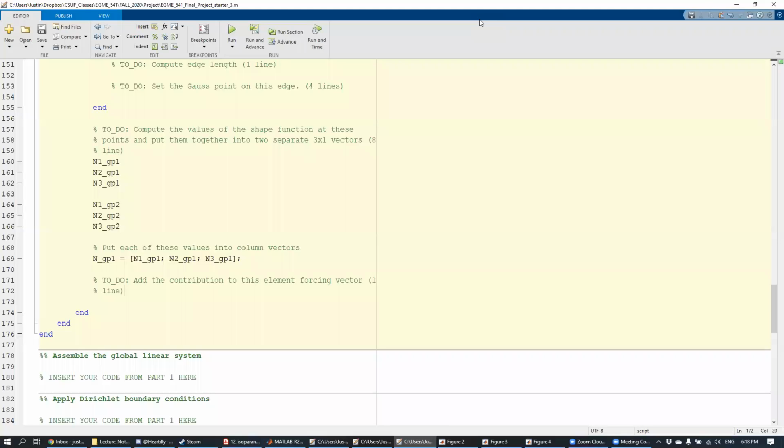Professor, the shape functions are going to be the same. So they have the same functional expression. So N1 is still going to be xi. N2 is going to be eta, N3 is going to be 1 minus xi minus eta. But when you evaluate them at the different Gauss points, they're going to end up with different values. Yeah, of course. Okay, thank you. Yep. Mm-hmm.